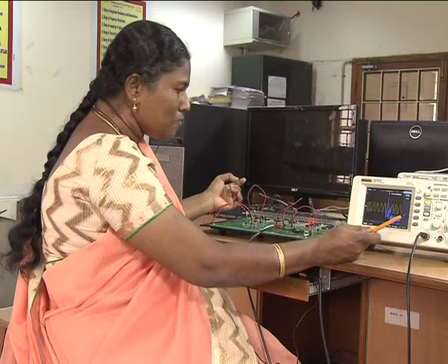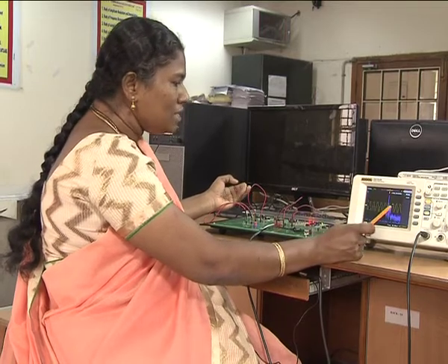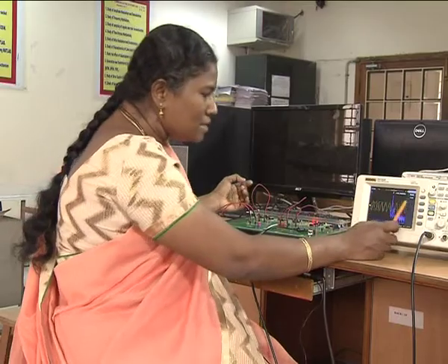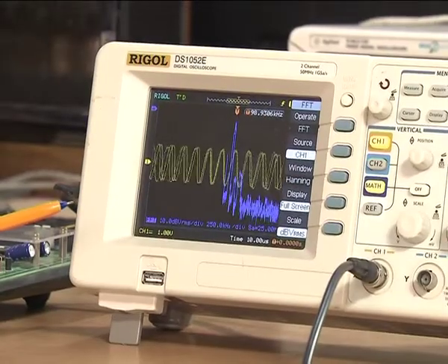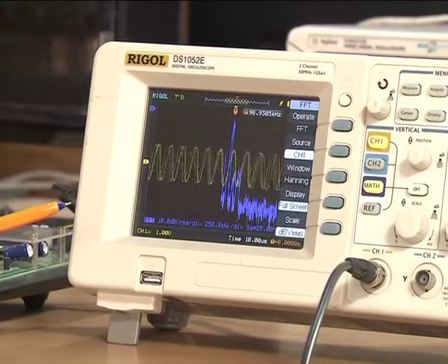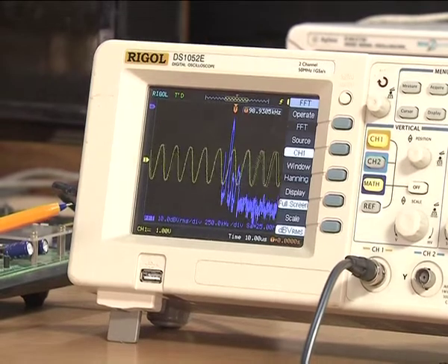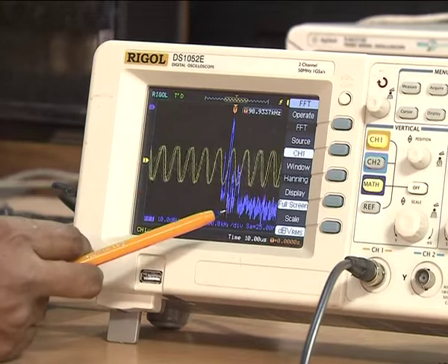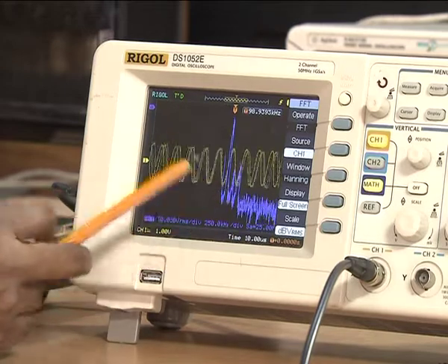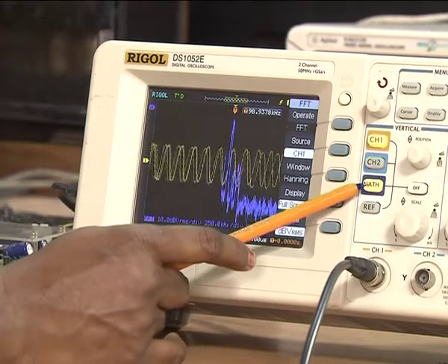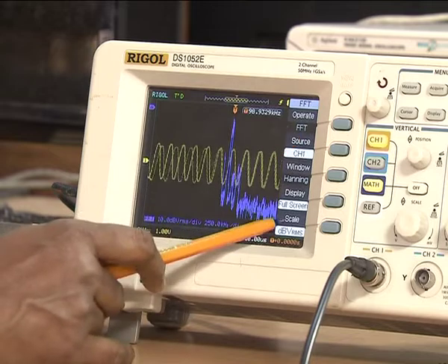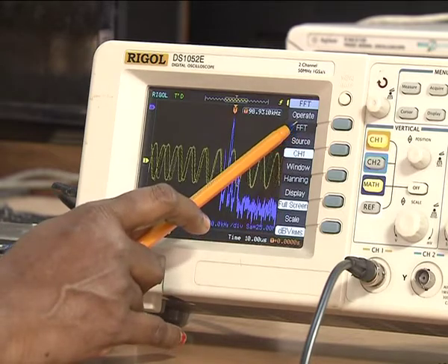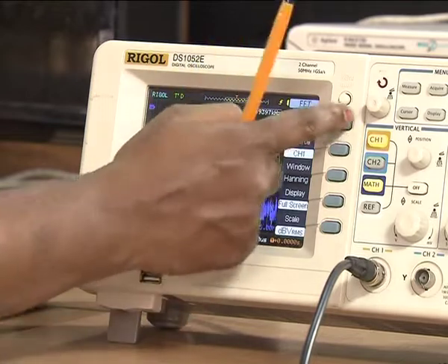f min by 2. To see f max and f min, we need to view the signal in the frequency domain, which can be done using the math function. To see the frequencies that are generated by the FM modulated signal, we can look in the FFT mode, which is available in all DSOs. To get the FFT mode, we need to press the math knob. When you press the math knob, this drop down window comes in. From this drop down window, we need to select the FFT operation. Once you select the FFT operation,